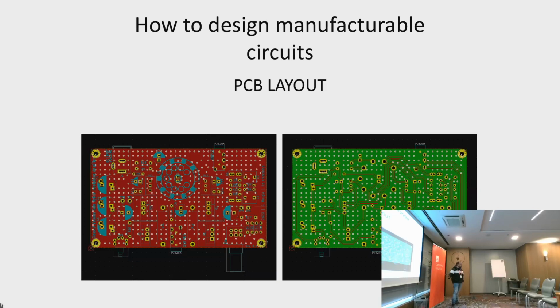Cool. But you will not have a button that does the layout for me. So you need to do it on your own. Usually you start with an auto layout and then start tweaking. That's what I often do, especially for complex circuits. It's a matter of choice. I don't think they have implemented an auto router within KiCad, but maybe you can have something with a third-party plugin.